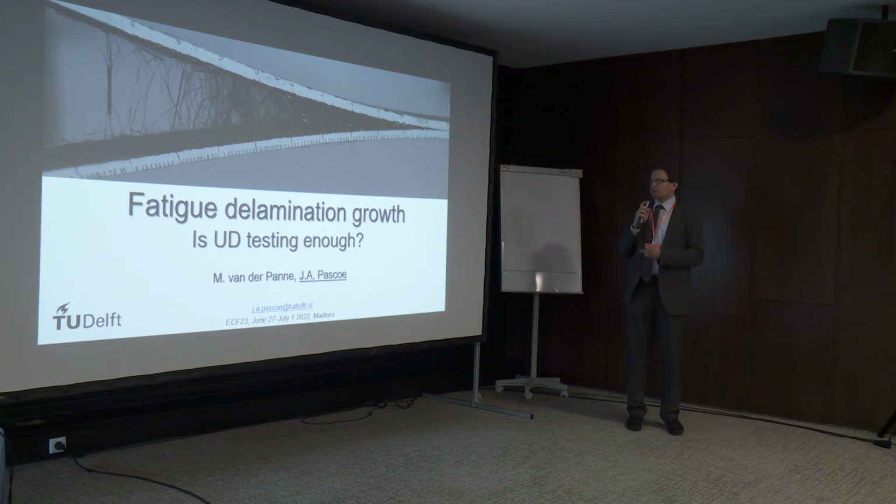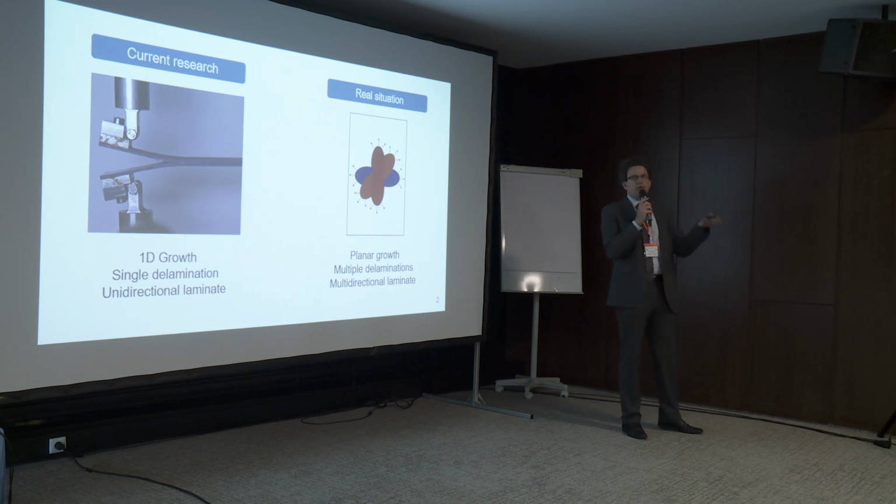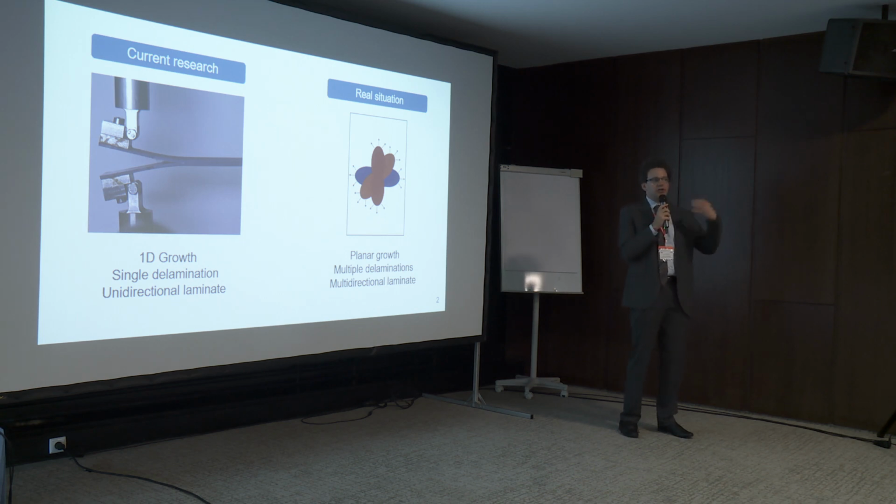And so, what is this related to? Well, fatigue delamination growth. Over the past 2 to 3 decades, when we've been studying that, we've been relying on these standardized test geometries, DCB, ENF, and so on. But why? I mean, if we look around this room, I don't see any DCB specimens in the structure of the building. Of course, the answer is that we hope to learn something from these standardized tests that we can generalize, that we can transfer to full-scale composite structures.